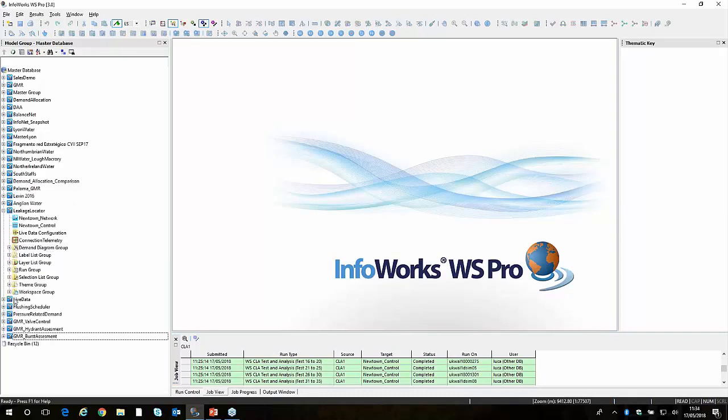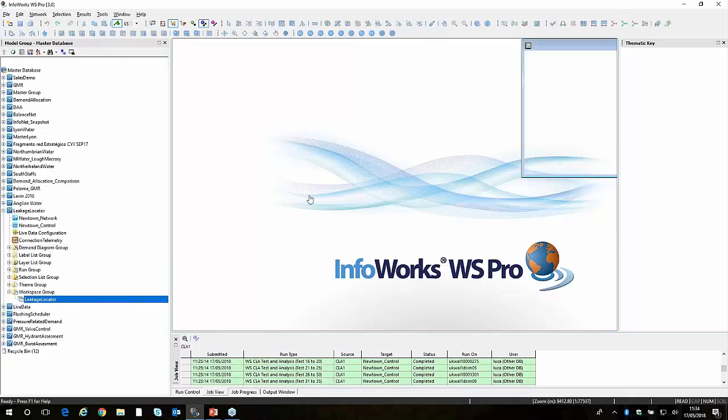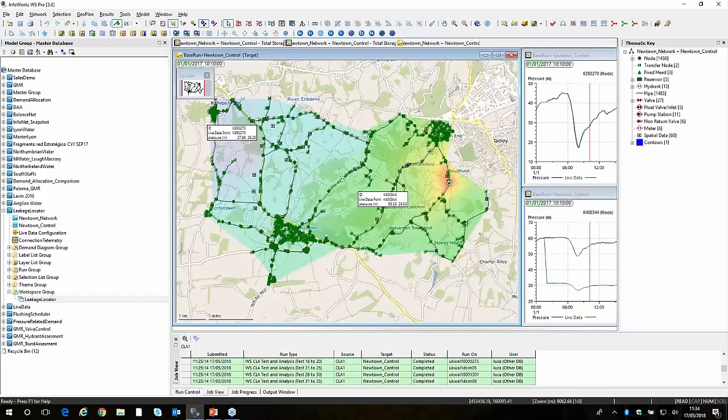So moving on now, on the PowerPoint presentation, I mentioned the ability to run a leakage locator run to basically identify where the leakage are on our system. I just want to start by saying that this type of simulation really relies on the quality of your model, on the amount of sensor that you have out on the field, and also on the leakage amount. So we will need the right combination of these three information in order to really locate the leakage using a